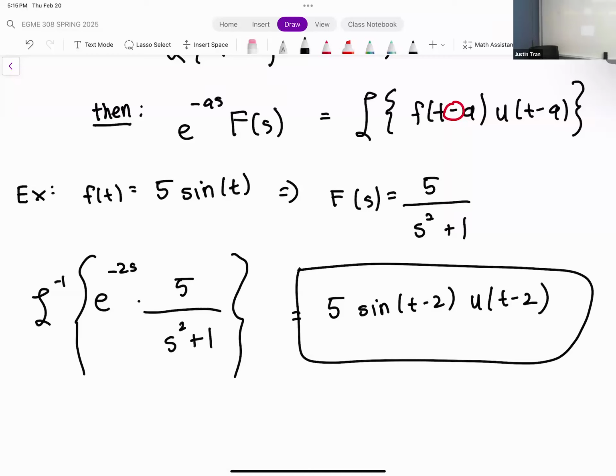It's a linear actuator, it goes up and down. I'm not the one running it. It's the robotics engineering team that I'm a mentor for. That's awesome. So the linear actuator goes up and down. Something is wrong with the down, because the motors make a funny noise, you can kind of see there's a small oscillation. Okay. I see.